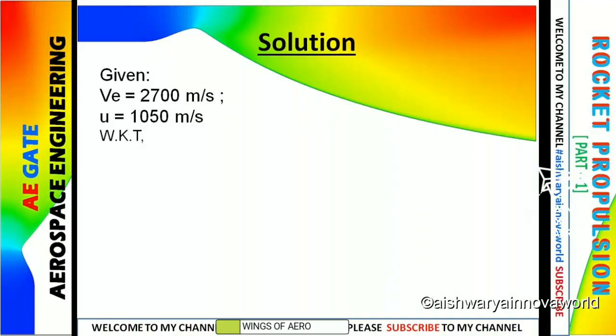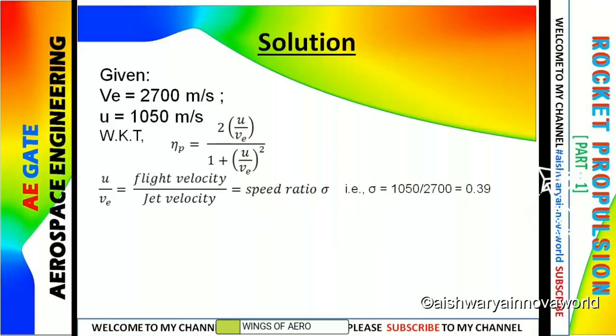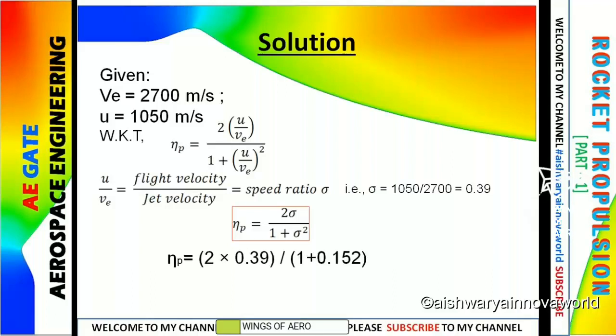So let's see the solution. We know the given data. Now we know the formula. What is this propulsive efficiency? Write down the formula. Then we can find the speed ratio, that is sigma equals 1050 by 2700. We get a 0.39 value, and after that use this formula with the sigma value, that is eta p equals 2 sigma by 1 plus sigma square. When you substitute, 0.39 square gives 0.152, and you simplify, you get 0.68. In the question they have given it in percentage.